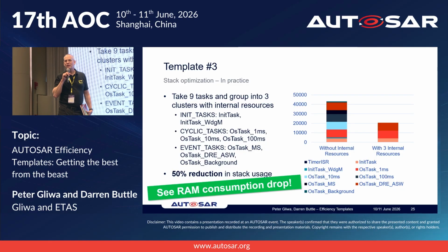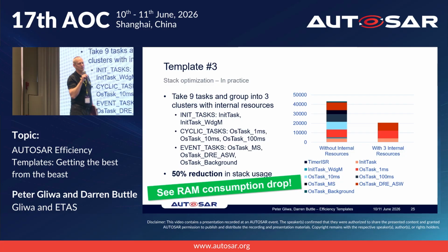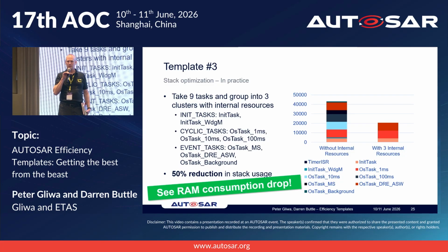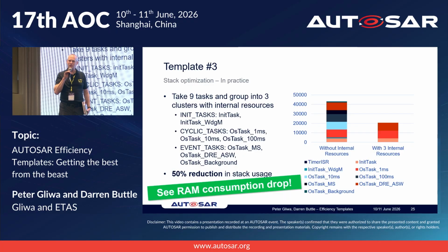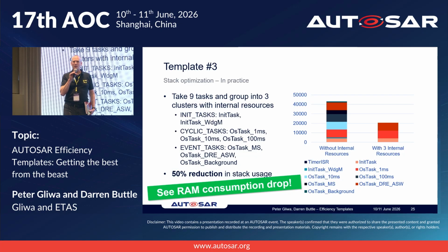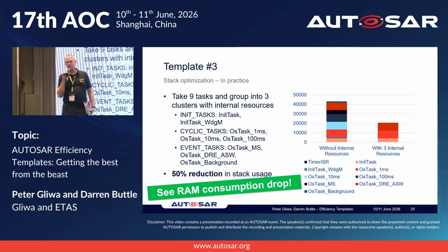Then we applied cooperative multitasking, which is a very, very nice approach that allows you to have task switches, but not at any point in time, rather in between runnables. So you're getting closer to the preemptive setup while eliminating some of the big disadvantages there.